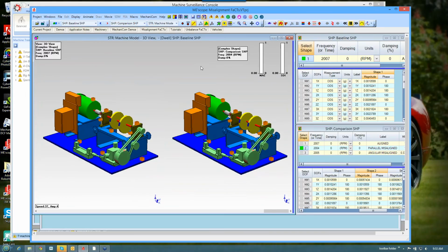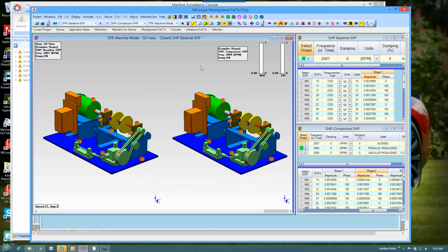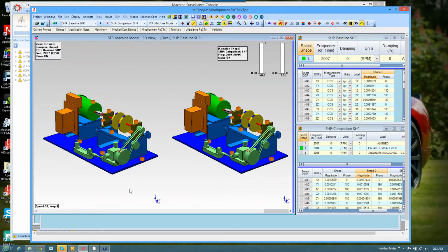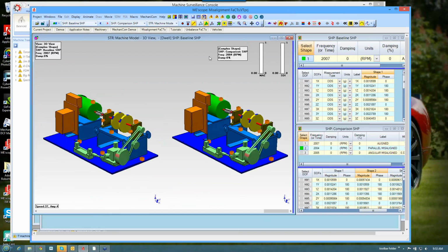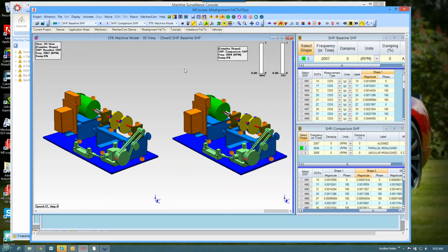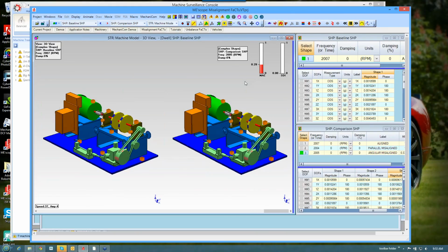So if I simply had 3 triaxials sitting on motor and bearings on this machine and it's running in the field, both MAC and SDI would show me very strongly what has happened if I've identified that case as parallel misalignment. Let's go to the angular misalignment. Again, very strong indication, both of them dropped, so angular misalignment is occurring or is being detected by just the motor and bearings.